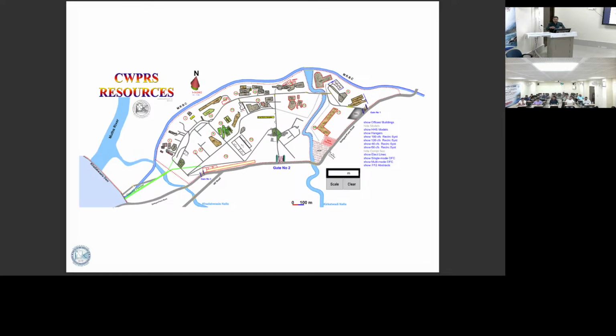In the model also we should take care of what I told you: space, discharge and head. So head will come into the picture. We have to design the model such that the top portion and bottom portion have some difference at each step. Then only you get free flow. Otherwise somewhere downstream your canal will be higher and your model will be lower. As I told earlier, backwater will be there, and that should not always be there. So in the model also we have to design in a proper way.